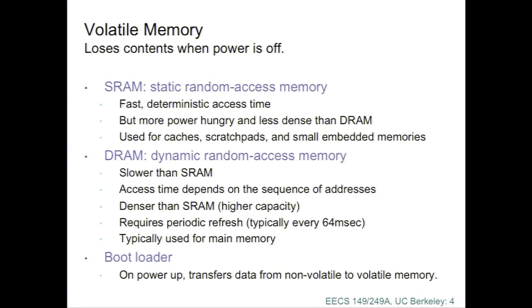One interesting thing you need to worry about with embedded systems, and with general purpose computers too, but it's kind of taken care of for you, is what happens when the power gets turned on. Your volatile memory has garbage in it. It could start up in an arbitrary state.